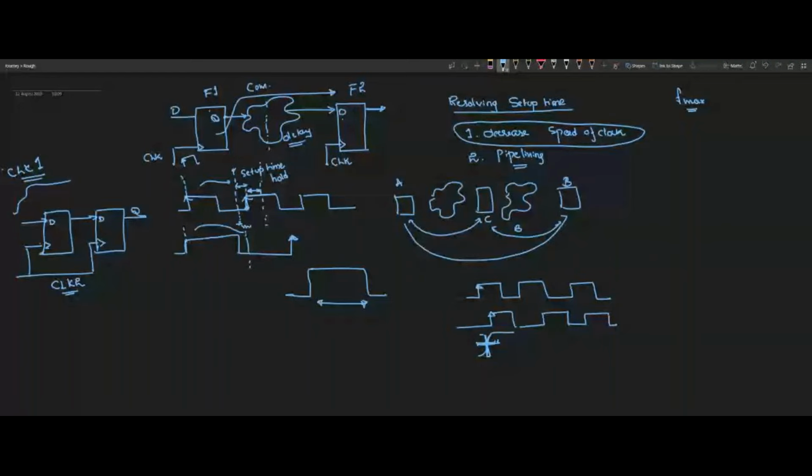You don't hear this term quite often, but it is also there, because that is mostly what we do, a simulation. We call it dynamic timing analysis. But static timing analysis is slightly exceptional. Here we are not bothered about functionality. Here we are bothered mostly about the delays, so we deal with delays.